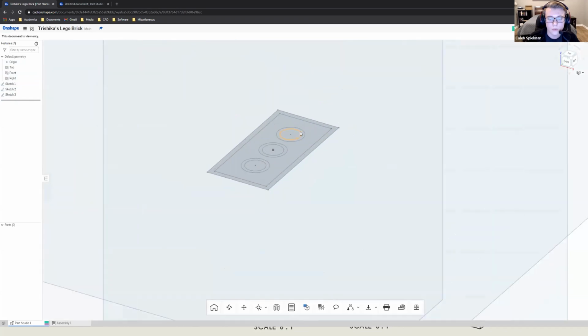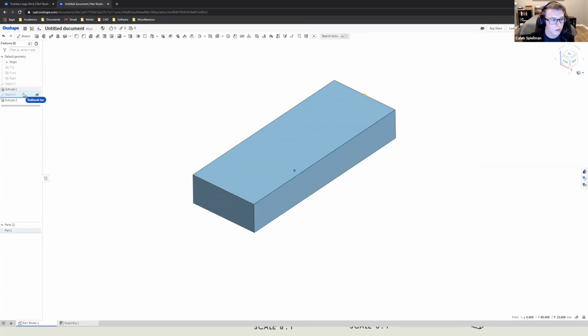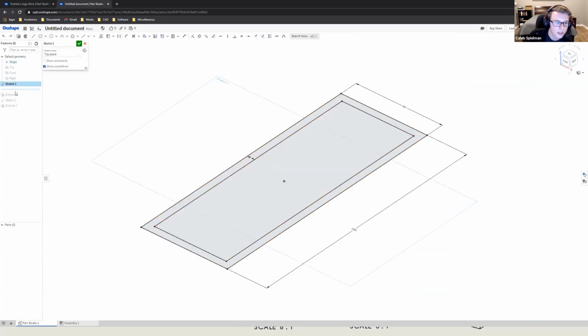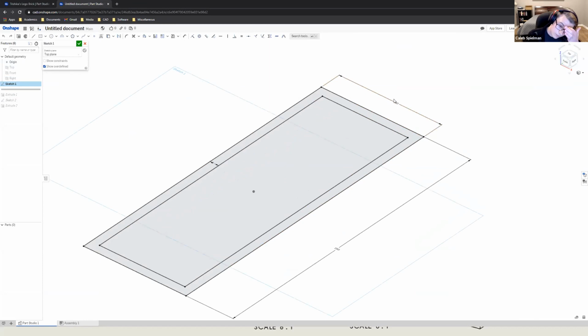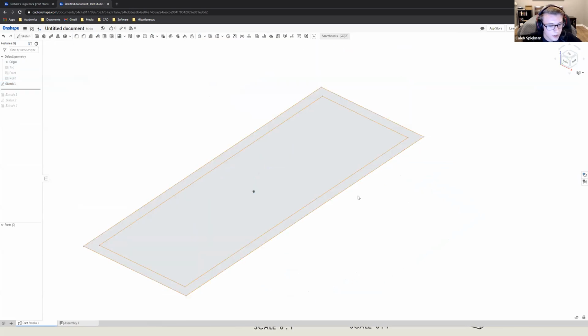All right. So from those sketches, I'll show you something quick here. I'll just roll all of this back. So from this sketch, I can open the sketch, I can edit it. Of course, I have my dimensions here. So from a sketch, the point here is to make a solid. And the feature that we want to use is the extrude. So I can show you where that is.